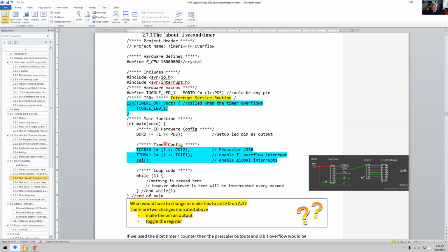But if you're going to reconfigure your timer at any time and change the prescaler, then you want to make sure that you are setting the right bits and clearing the bits you need to clear as well. That's this whole concept of state. You need to understand that the state the microcontroller is in now is defined by its previous state. We know the previous state at power up: all the register bits are 0, so we can just set the one we need. But later on, you might be unclear about the state of these 3 register bits, so you need to make sure you set and clear the bits you need. I'm going to go on about that concept of state.